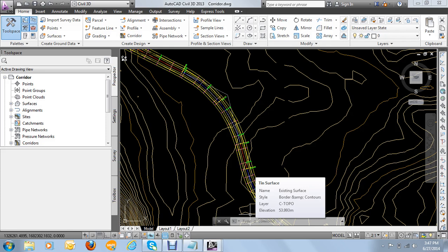But you make sure that the standards you are inputting correspond with everywhere, where maybe you imported the values for the lane or shoulder. And from there, because when you are creating a corridor, all those things will be asked. So without them, we won't create it. And on top of all, you cannot create a road where you don't even know what the components of the road are, what type of lane and what standards. You don't have them, so you won't create it. I don't know if I have answered your question.